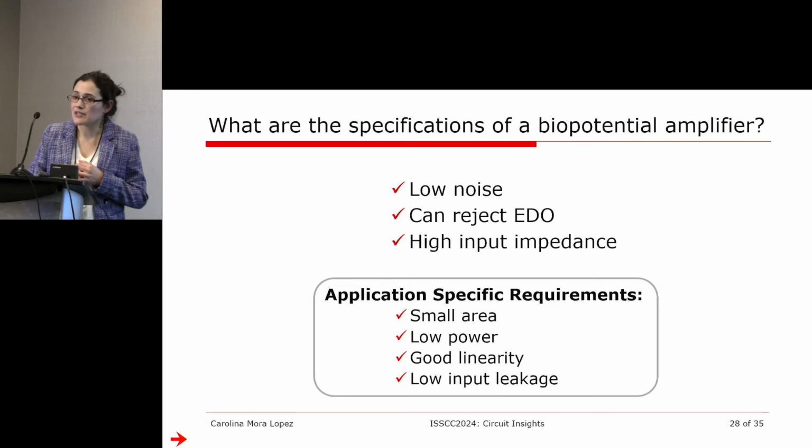But there are many other techniques. There are also some disadvantages of having that capacitor. For example, indeed, if you want a higher input impedance for certain applications, that's very important. And a capacitor won't be good enough. So other people have implemented, for example, DC servo loops or other feedback techniques that get very, very complicated in implementation. But for some applications, that's worth it because it achieves the performance that is wanted. Thank you.